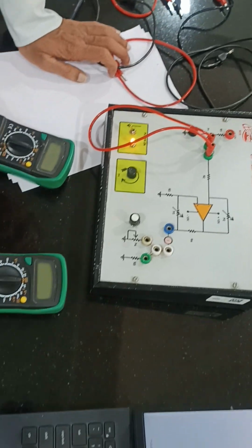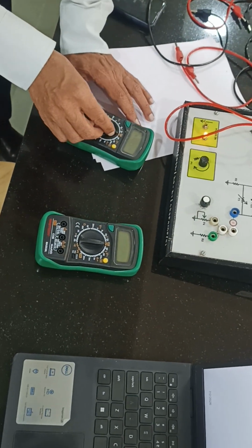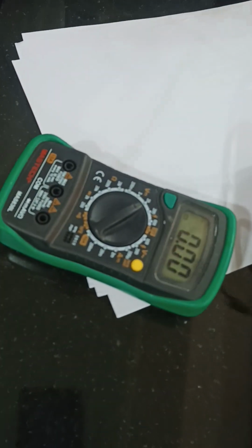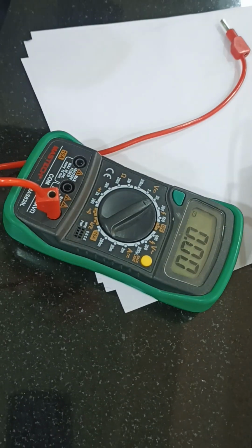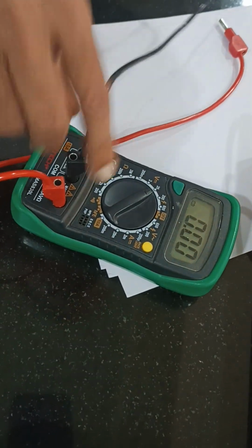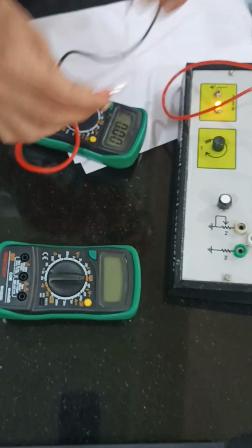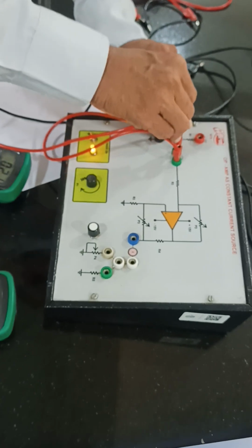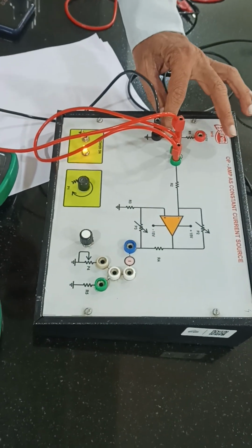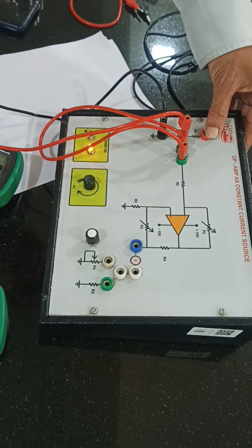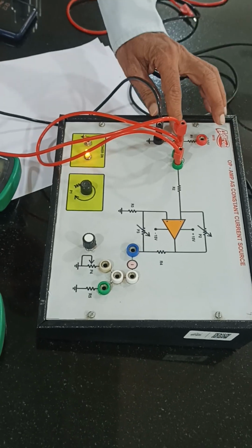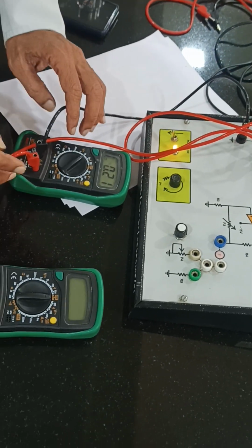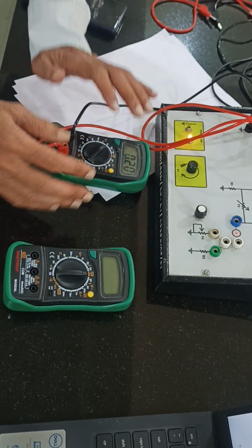Use one multimeter as a voltmeter. So what I will do, I will keep the multimeter on 20 volts DC. Then I will insert one terminal here, another terminal here, and then I will connect this multimeter across the power supply like this. Remember, we are going to connect the terminal here and not here, because this is a fixed voltage terminal and this is a variable voltage terminal, so the voltage can be measured. So this is being used as a voltmeter.